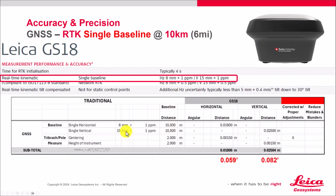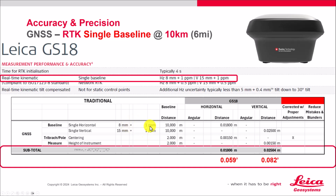And we have these different accuracies for the real-time kinematic vector. Plug all those in, and it comes down to 0.01806 horizontal and 0.02504 vertical, and so about 600ths and 800ths horizontally and vertically respectively.